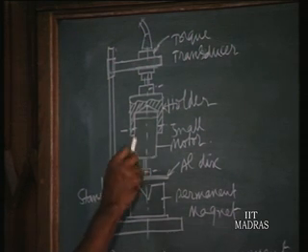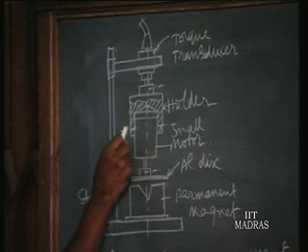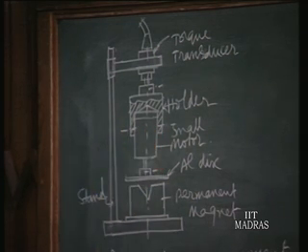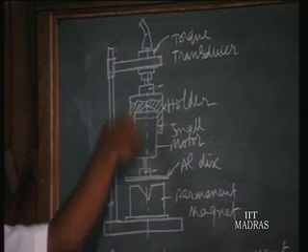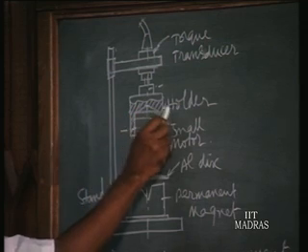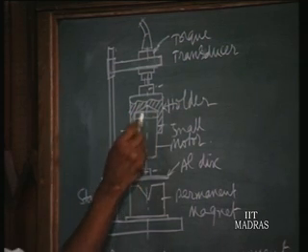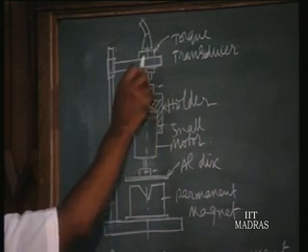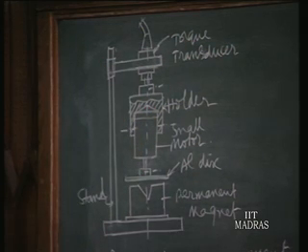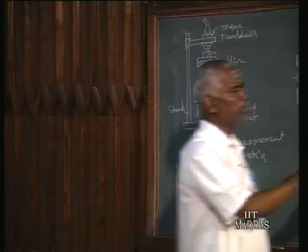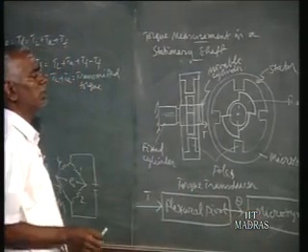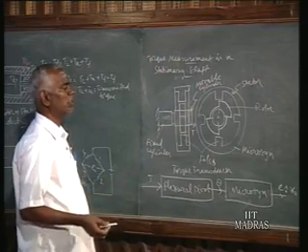That is, now the whole motor is held in a holder by fixing two screws to the stator of the motor. This is hung from a stand. So this is a holder connecting the motor stator to the torque transducer here. It transduces the torque in terms of voltage. How it functions, one principle we can explain here: how the torque is converted in terms of voltage.